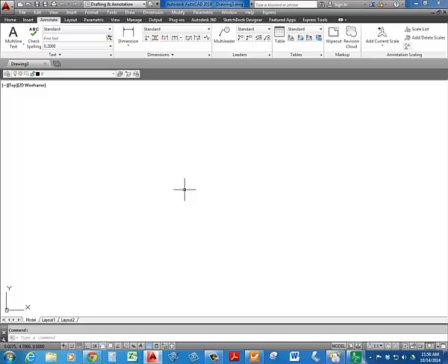Okay? If you've got a house plan and you want it to fit on an 8.5 by 11 sheet, you don't draw the house to scale. You draw the house full size in CAD. So if it's a 40-foot long house, you're going to draw lines that are 40 foot long. Then when you go to print it, we scale it down using a scaling procedure in the layouts. So we make the scaling process separate.